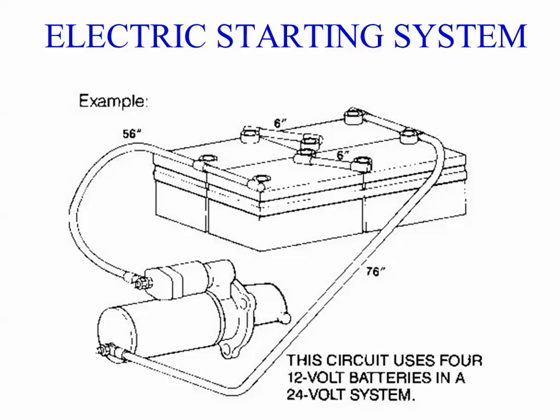And can you imagine, on your car, if you look at the cable on your battery, having to run that up under the steering column? So literally you're using less than an amp in the starting switch to handle 200 to 400 amps going to the motor.